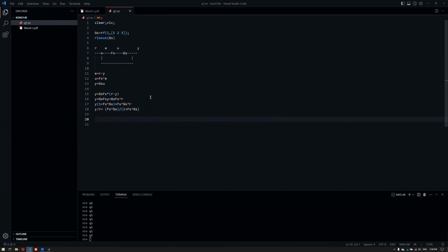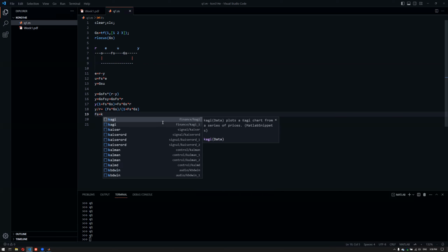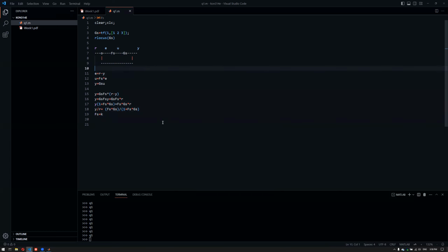Now, the easiest controller in the closed loop or unit feedback loop that we have drawn here is basically the static controller, or just a gain as a controller. So when we plug in F(s) equals K, which is also called the proportional controller Kp or K, it's proportional because it is generating the control signal, or the input to the system, proportionally to the error at hand. So it's basically U equals K times E, so it's proportional. Therefore, we call it the proportional controller or P controller.